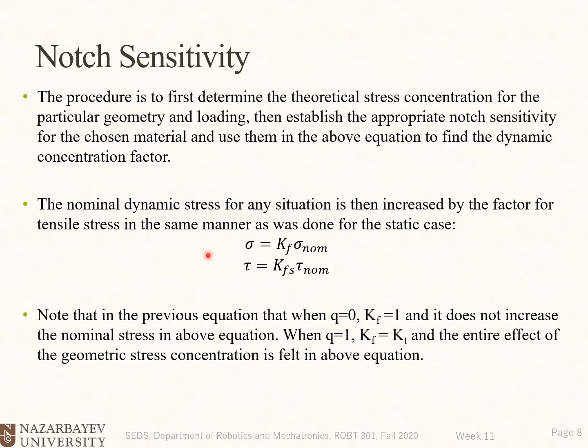The procedure is to first determine the theoretical stress concentration factor for the particular geometry and loading, then establish the appropriate notch sensitivity for the chosen material and use them in the above equation to find the dynamic concentration factor. Okay. The nominal dynamic stress for any situation is then increased by the factor for tensile stress in the same manner as was done for the static case. So this is the nominal stress.